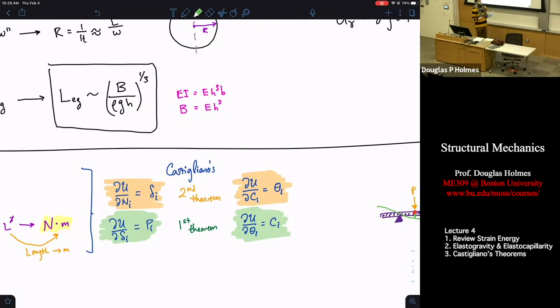A second way is, are your strain energies written in terms of the integral over some continuous dimension? Just like any integral, you could also discretize that object. And instead of having an integral over something, it could be a summation over all the, say, forces and geometric properties of each component. So say you had a truss, like 6 bars and 6 pins. You could write down a different version of Castigliano's theorem, which would be a discrete version,